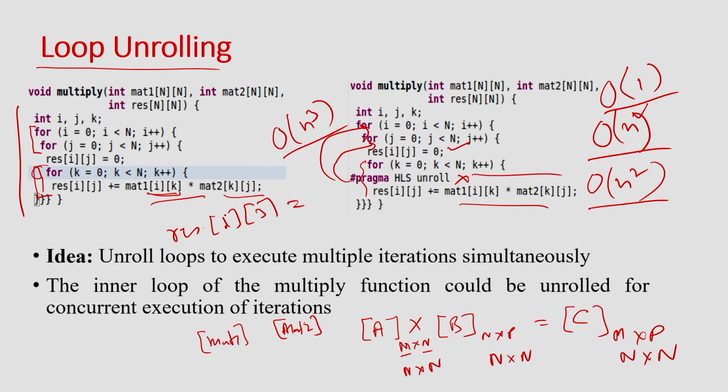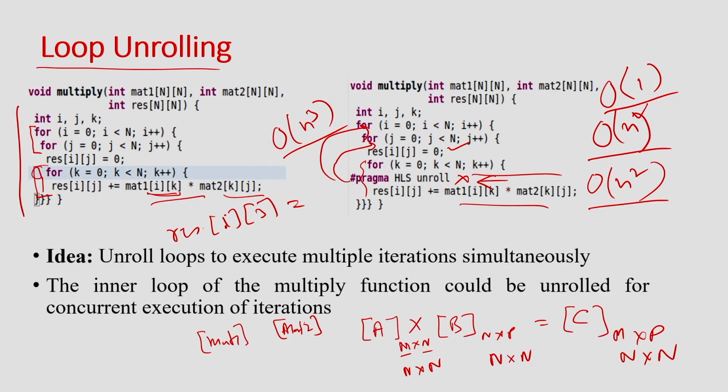Order of n cube multipliers: if you just think about n equal to 10, it is basically 1000 multipliers, which is not available in many target devices, right. So, you need to make a proper balance of that. So, what I am going to do is take this particular example and put this unroll in the innermost loop and see how it is going to impact the performance.